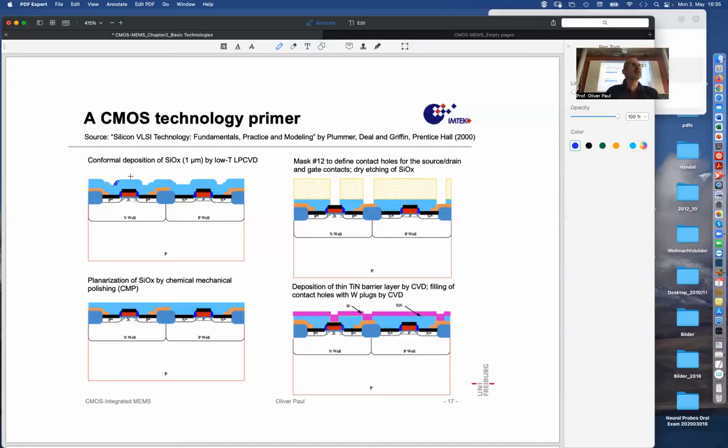Not a good idea. I've seen it happen at a company 25 years ago. I can't tell the name. Microelectronique Marin, our partner in developing microsensors based on their CMOS process, was a 1 micron CMOS process. Then, at some point they had this problem, and big trouble. So the etching condition was not well controlled. You need probably to do some over etching, sufficient over etching to remove even that little piece, and during that over etching, your metal lines also shrink, and so you better have a mask that is a bit larger.